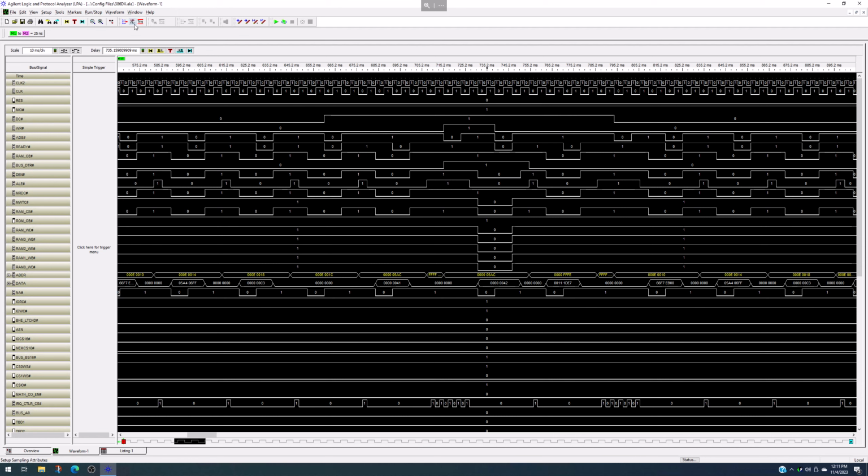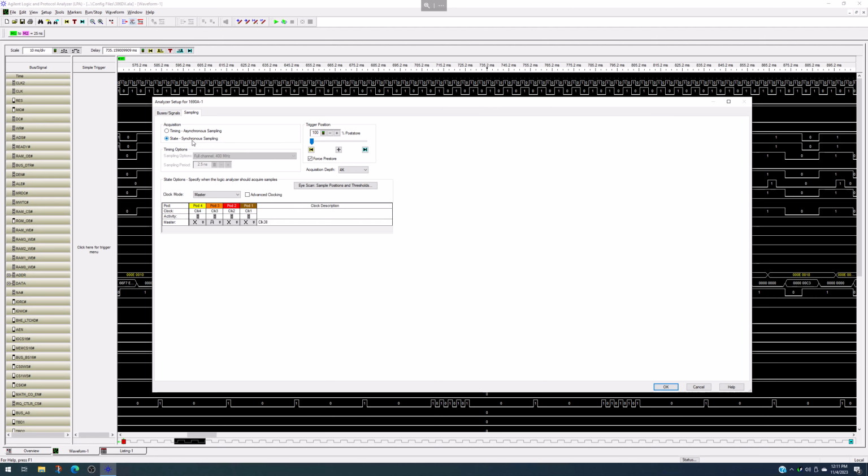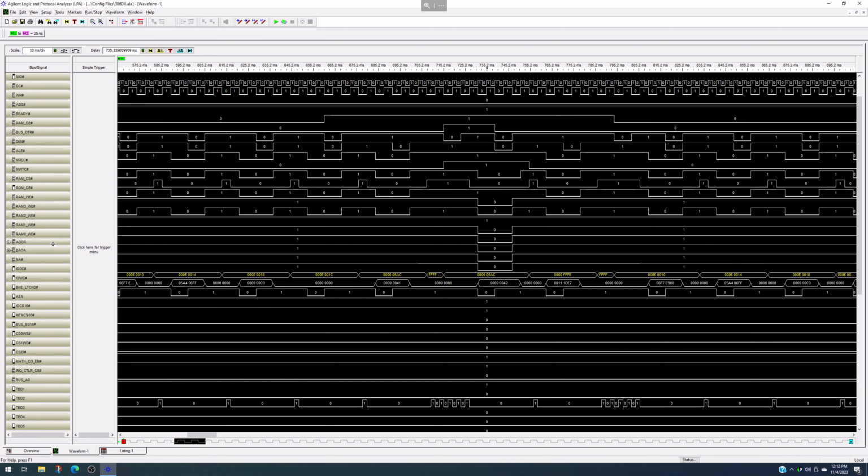Now in this case, if I go into how I'm acquiring, again, I'm doing it based on this clock. So I'm saying if that clock, and clock 3 and 4 are identical, 1 and 2 are identical. So whether I did 4 or 3, it really doesn't matter, I guess. But this is saying capture 4K of data if this clock signal, which in my case was clock 2, either moves up or moves down. And I did it for all of these signals.